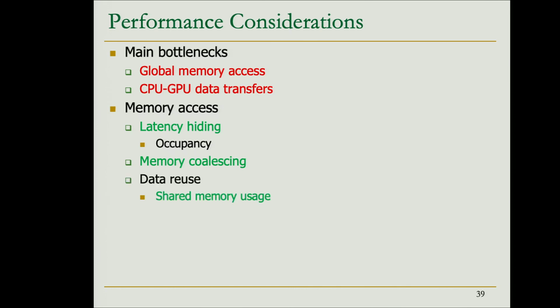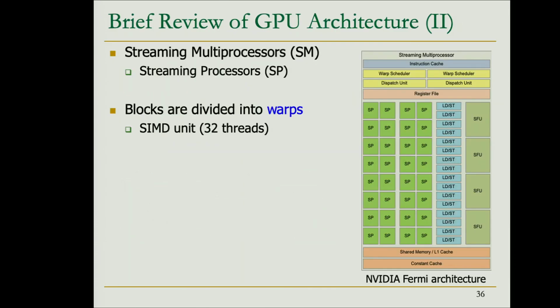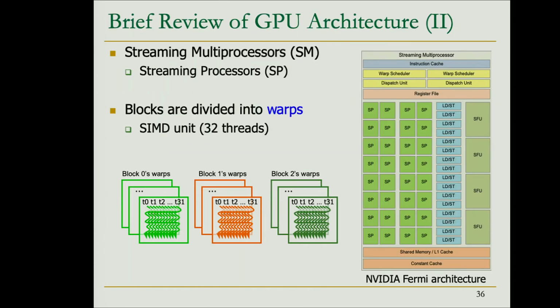And then we will also see how to use the shared memory that we have. Let me go very quickly back. It's right here. It's this shared memory that, maybe not in all GPUs, but typically is the same memory space as the L1 cache, and is internal to the stream processor or GPU core. So that's why all these units that we have here can access these shared memories, a scratchpad on-chip memory.